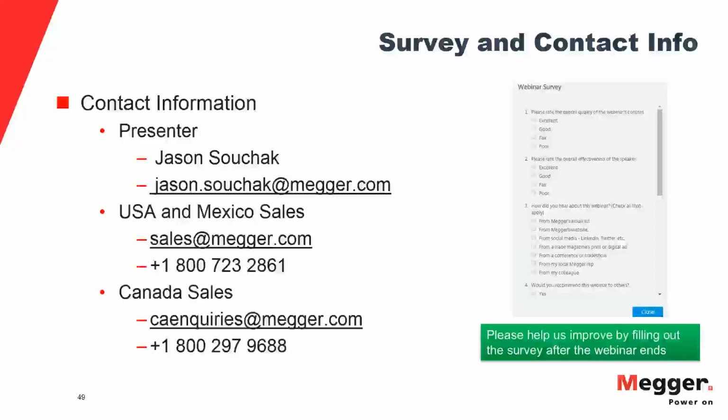Just one more word. Keep in mind what Jason spoke about, what you also saw in the test results, and what experience from Europe since the early 2000s tells: the defects you are after with PD diagnostics are generally in the hundreds of picocoulomb. Defects in accessories, localized, isolated weak spots, as the technical term is, like the shield got extruded into the main insulation, or semicon tape missing, whatever. These manufacturing defects are, to be honest, very, very rare.